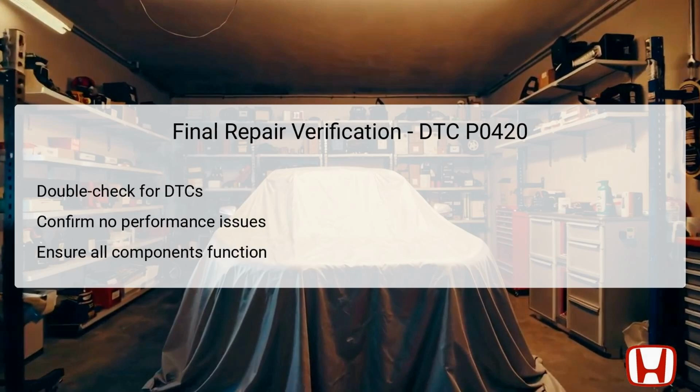After completing the necessary repairs for DTC P0420, it is essential to perform a final verification to ensure that the issue has been resolved effectively. Start by double-checking for any DTC codes using the HDS, ensuring that no error codes are present post-repair. Next, assess whether the vehicle shows any signs of performance issues directly related to the engine and exhaust systems. The system should work seamlessly without triggers coming from the diagnostics.